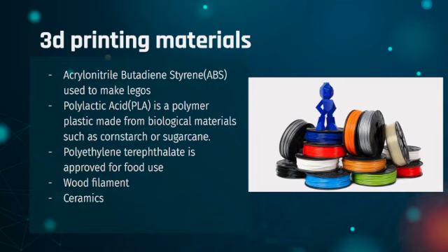And so when you're deciding what 3D printing materials you should choose, you have to factor in application, function, or design. 3D printing materials come in many different forms. Most consumer 3D printed products are made from plastics. In plastic, there's acrylonitrile butadiene styrene, or ABS, which is the plastic used in Legos. It's tough, non-toxic, and retains its color well. It also is easily shaped as it melts, so it's easy to mass produce.